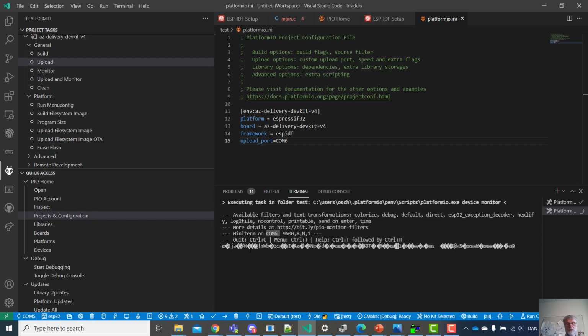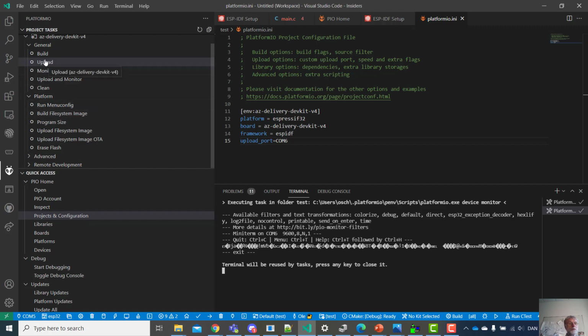The reason for these weird things is it is set up for the baud rate of 9600, and it is 115200 we should go for. So we need to show running tasks. Control C to exit.